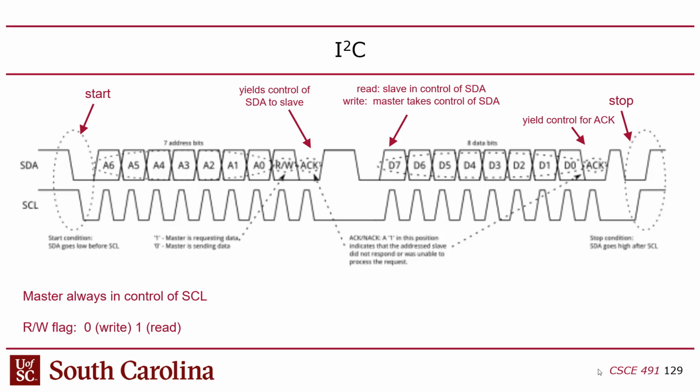So the important thing to understand about that, as with any latch, is that because the data is being read when the clock is high, in this case, because it's level sensitive, you don't want to change the data when the clock is high. So you want to set your data, get it ready. And when I say data, I'm talking about the data line, SDA.